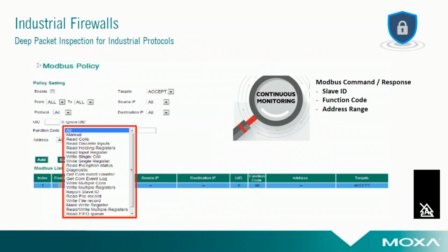So in an industrial firewall, typically we try to make it a little easier for people to implement by having these quick automation profiles built in, so that if I'm running Ethernet IP over a specific segment and I know I need that type of traffic to be whitelisted, I can just go into the drop down here and activate Ethernet IP as the type of traffic that's allowed.